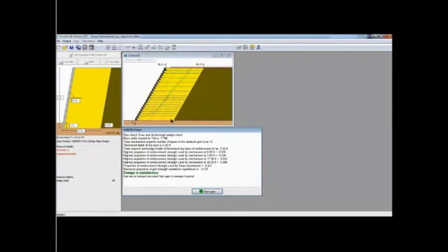But this gives us an efficient way of designing the geogrid in an optimal way, so that way you can efficiently and quickly come up with a layout for your geogrid which you can use to put into your global stability software for a final check. Once you're done, you can click on either of the print features and move forward with your printing of your calculation.